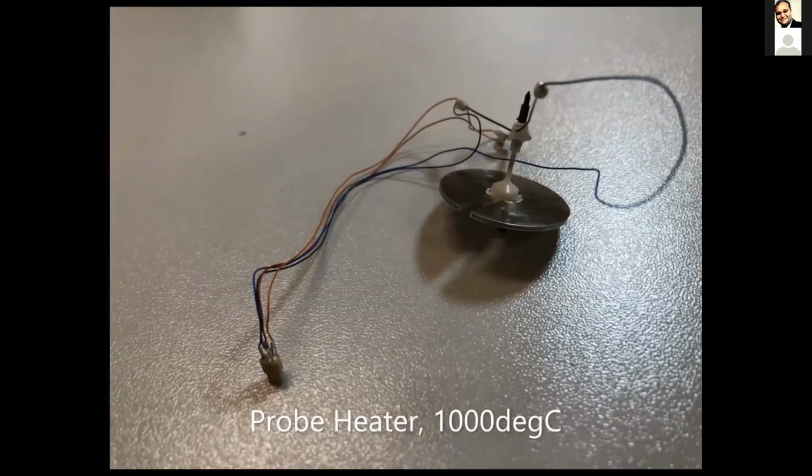This is very important because probe wear at high temperature testing is always a concern. The high temperature aids chemical reactions that occur between your tip and your sample. In this case, we're using a 20 micron diamond flat punch, which can work very well in vacuum.